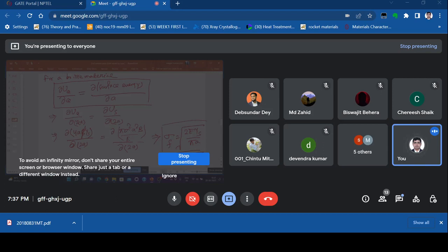So that is basically the critical value of the stress intensity factor, we can say. Fracture toughness, if you consider mode 1, this is our expression. Here a is the critical or any length of crack. There is a trade-off between sigma and a. If your sigma is high, then the critical length of crack will be small.